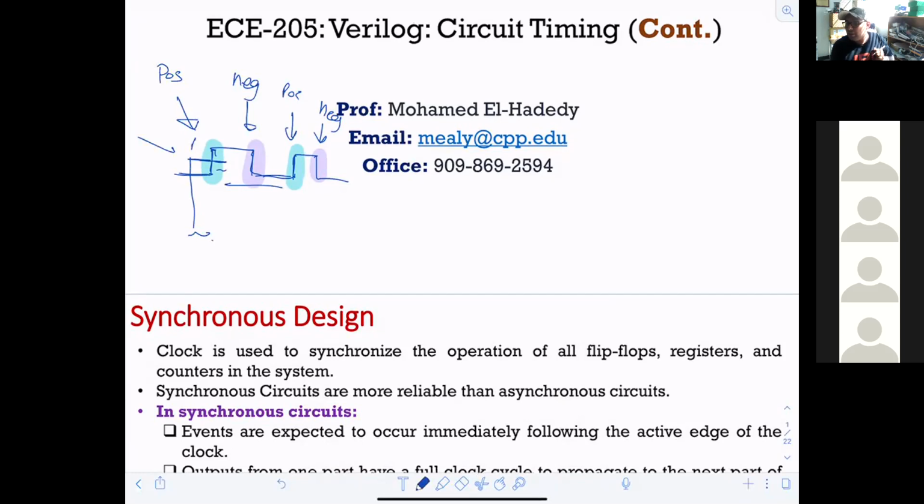In something called metastability. That means the output will be crazy. Might see a 1 as an output, sometimes you see a 0, sometimes an X. Why? Because any wire can hold X or 0 or 1 or even Z. Z, high impedance, that means this wire is floating, flying in the air. Nothing's connected. X, that means I have no idea, I don't care what is going on inside this wire. 0, that means it's connected to the ground. 1, it means it's connected to the source. Do you guys agree?